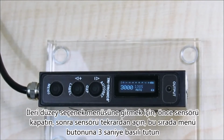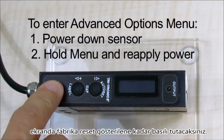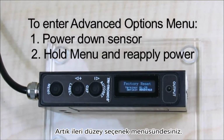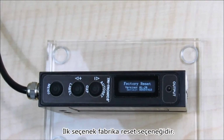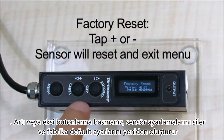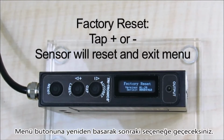To enter the Advanced Options menu, first power down the sensor. Then reapply power to the sensor while holding down the menu button for 3 seconds, until you see Factory Reset displayed on the screen. You are now in the Advanced Options menu. The first option is Factory Reset. Tapping either the plus or minus button will clear the sensor settings and restore factory defaults. Tapping the menu button will advance to the next option.